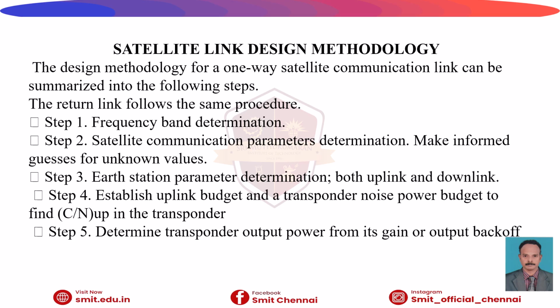So what is this link design methodology, which is one of the most important engineering procedures in satellite communication? So far we have studied the satellite basics, uplink and downlink, as well as the link budgets, the carrier to noise ratio, the G/T ratio, as well as the link margin. Now we are going to deal with the satellite link design, which involves the design parameters required for successful communication. So the design must have a required signal quality.